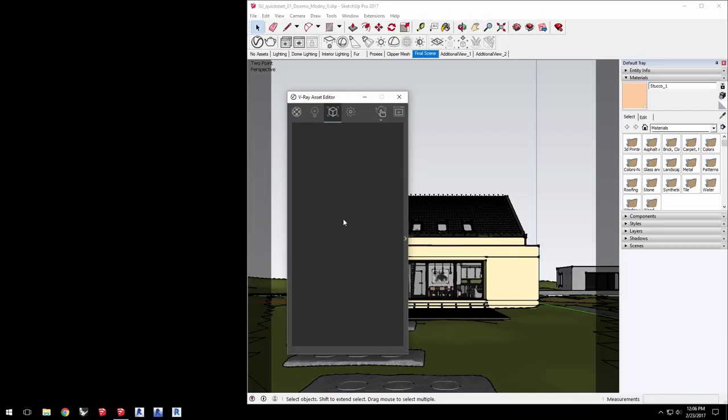The next icon over is the Geometry Editor, which would list any V-Ray specific geometry in the scene, such as fur. The Gear icon takes us to the 4th and last section, Settings, which gives us access to edit the render options for the scene. The icons in the upper right are a render button and a button to show or hide the VFB, just like in the main toolbar. Now let's start an interactive render. Make sure your settings match a scene here and click the render button to get going.